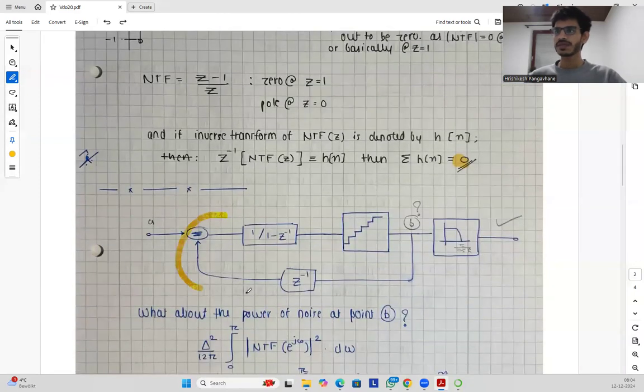Then we said we'll implement it in a block diagram. We saw this block diagram where we have the input, then the difference over here, and then a first order transfer function. We are all aware of this transfer function: to see the phenomenon of noise shaping, we have a very high gain at low frequencies, but the gain drops as the frequency increases.